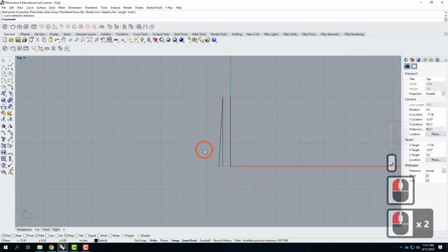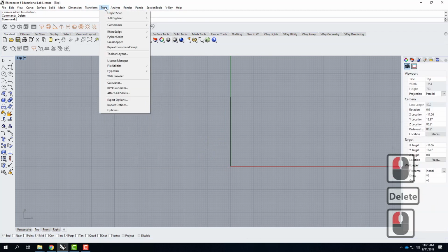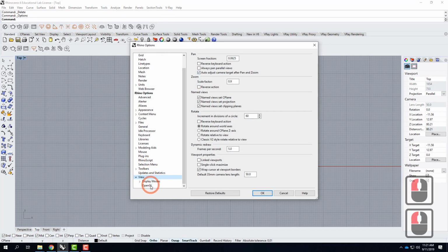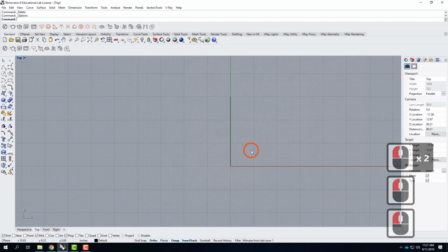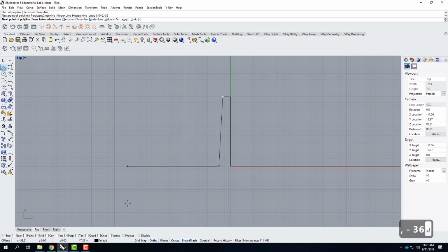that's an awful lot of work. I turned off my OpenGL, so hold on a second. There we go. Now I'll be able to see everything. So here, using those relative coordinates, I would type in the @ sign first, and this would be at -2, -36, and I can create that without having to do any slides or anything. It's a bit easier to go ahead and establish that.